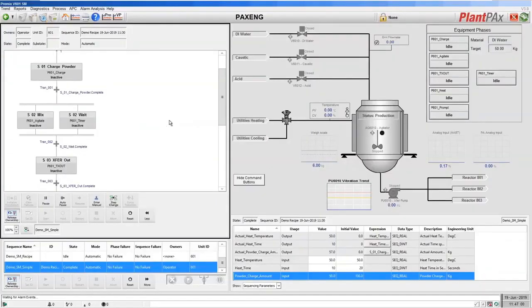Having used that free library for our control modules, the next layer in S88 is something called an equipment module. This is basically a way of simplifying a complex set of operations. For example, maybe you wish to route from one tank to another, you have a set of routing valves, you have many different routes, and you want to simplify the control. You might decide that one way of doing that is to use an equipment module where you can put it into not being used, or route 1 or route 2 or route 3 for example, and it controls the sequence of steps to move from one route to another. In our simple example, we don't have any complicated situations like that, so there's no need for any equipment modules.